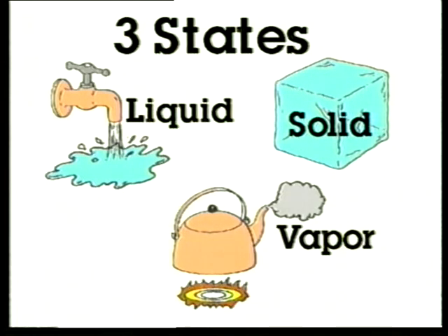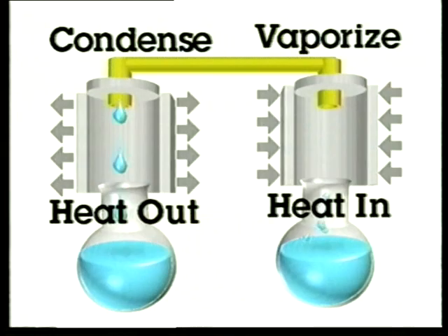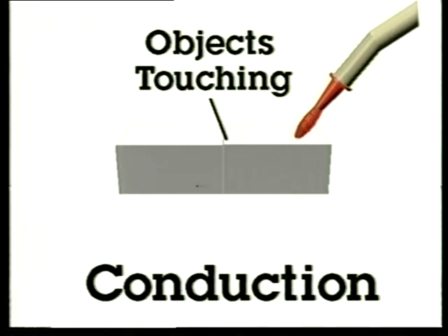When a gas condenses into a liquid, heat is released to surrounding objects. However, when the liquid vaporizes into a gas, heat is absorbed. Since cold is really the absence of heat, this is important to refrigeration because the refrigerant is forced to change from a liquid into a gas, then back from a gas to a liquid. This makes the system absorb heat during vaporization to produce cooling, then release heat during condensation.